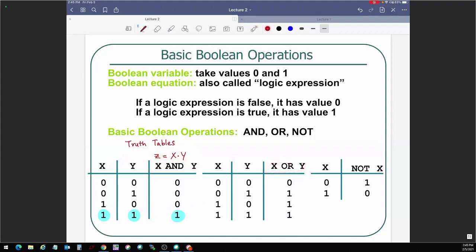And now we can also have, say, A equals X OR Y. And as you can see, we are using the plus sign to indicate the OR operation. This or this, right? One or the other. If it is true, then the output is true. So you see, it is true here, it is true here, and over here, both of them are true. So those are the three cases in which at least one input binary variable is true, leading to the output becoming a 1 for those three cases. That's your OR logic operation.